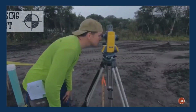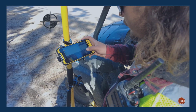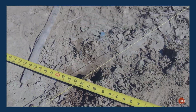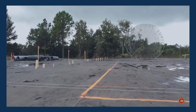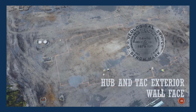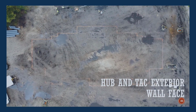There are various ways to lay out a building, whether it is the older school method or by GPS. The job has to get done. Let's look at the old school method. Happens 2 ways. The first, a surveyor lays out secondary control points off of established primary controls, such as installing hub and tack to identify the column lines and exterior wall face lines with offsets.